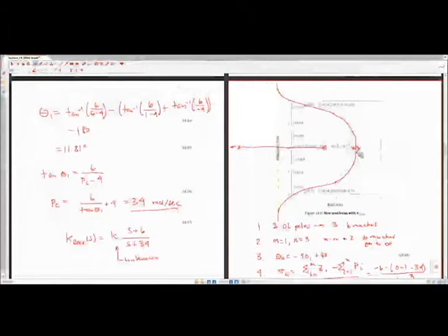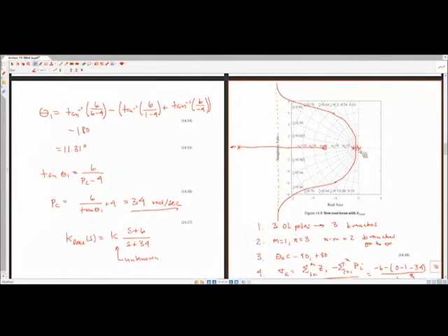All right, so it has to break away from the real axis, and it has to break away on a point on the root locus. The other 2 options are not on the real axis, right? Those are complex numbers. This is the only one on the real axis, and it's also in a region where the root locus exists on the real axis.